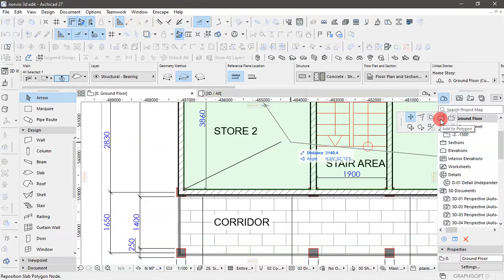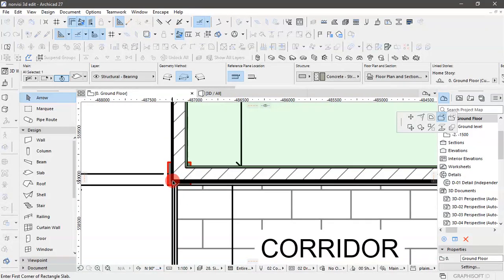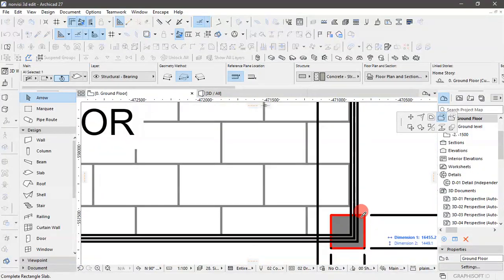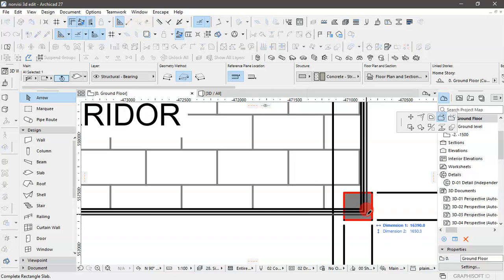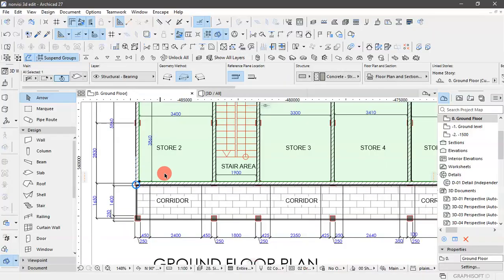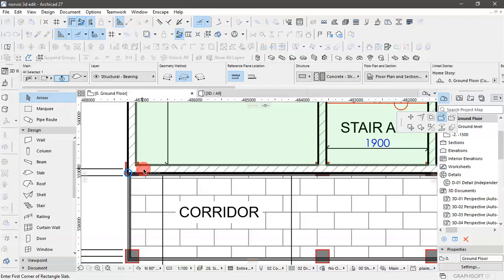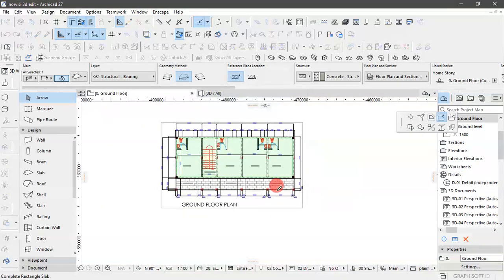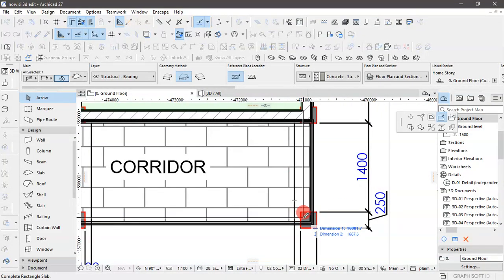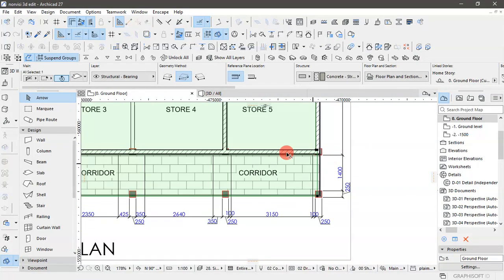I have slab. Click on this plus and then there's slab. Make sure it's slab, all the way here. Okay. It didn't appear because it wasn't joined to this slab. It has to be joined to this slab. So we can go to this, click here. Okay, then move all the way to this side. Okay. So now it has come.